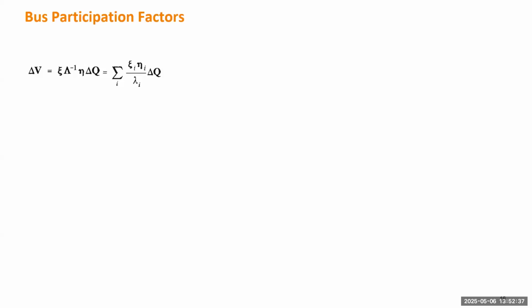Okay, so you remember in small signal stability, we mentioned one concept, which is the power participation factor. Participation factor is very useful because it utilizes both the mode shape and mode composition to determine the two-way linkages between the mode and the state. So for any participation factor to be high, that will be the ideal location where you can implement the control.